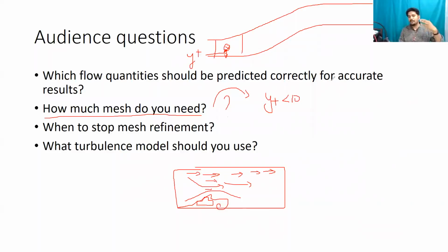For example, if you take the K epsilon turbulence model, which is very popular. Why is it popular among students? Well, in most software, that is the first model available, so people just leave it. When you're using K epsilon, depending upon the implementation, it might not be able to handle adverse pressure gradient, meaning whenever flow separates, that turbulence model is no longer valid. It does not have the right terms in the equation to solve it, right? So these are the things that you need to question.